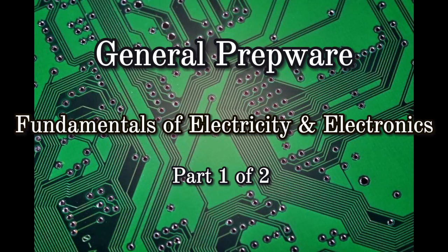A lead-acid battery with 12 cells connected in series, no load voltage equaling 2.1 volts per cell, furnishes 10 amperes to a load of 2 ohms resistance. The internal resistance of the battery in this instance is 0.52 ohm.